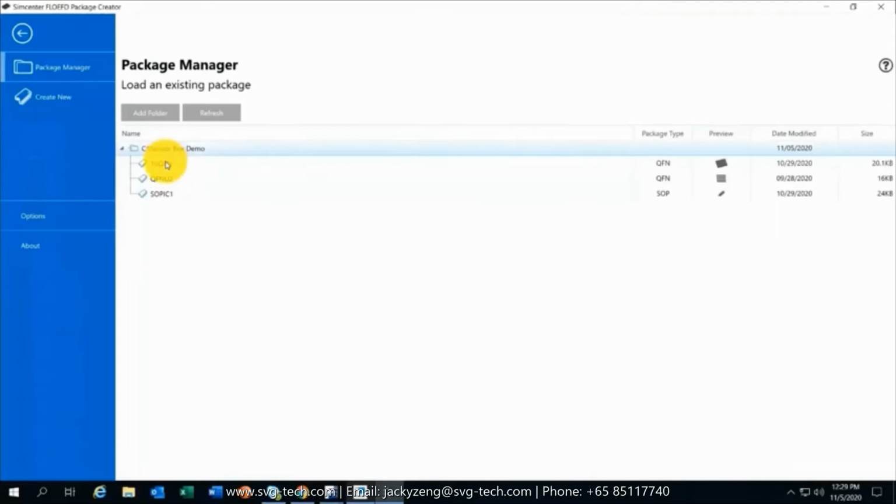So yeah, the next thing I'm going to show you here is something known as the package creator. The package creator is a way to model IC packages, MOSFETs, etc., in a higher level of detail than just a 2-resistor or simple block-like representation. So what the package creator does is it lets you create packages using a template-based approach. You can also create a library. As you can see here, I have a library of a few components over here. These 3 components in my library.